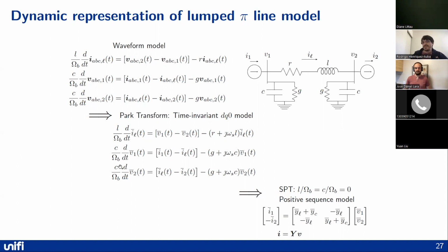As an additional note, it's important to be aware that when you use singular perturbation theory to reduce network dynamics, you have to consider how fast your device models are, to ensure consistency between the equations that you're using. For example, it's common that when you eliminate line dynamics, you should also eliminate the stator fluxes in machine models, and those are on similar time scales.